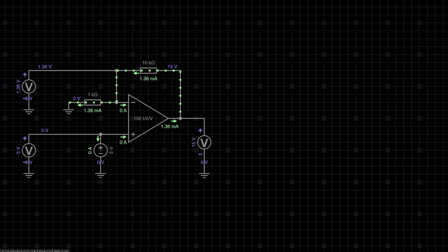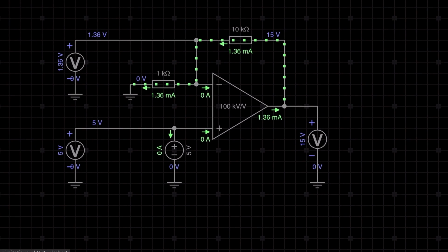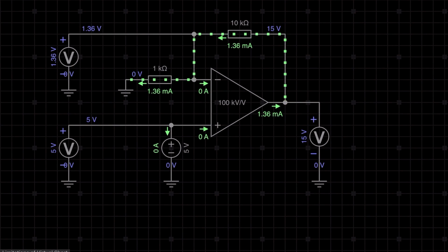We already understand the first limitation. That means if the op amp works in the saturation region, then virtual short will not work. Okay. Now going to the next one, that means the open loop gain. In my last video about the virtual short, I already explained that if we consider the open loop gain AOL in the calculation, then if the gain is greater than 10 to the power 4, we can consider virtual short. Otherwise, no, right? Otherwise, if we consider virtual short, then the output voltage V0 will be lower, right?